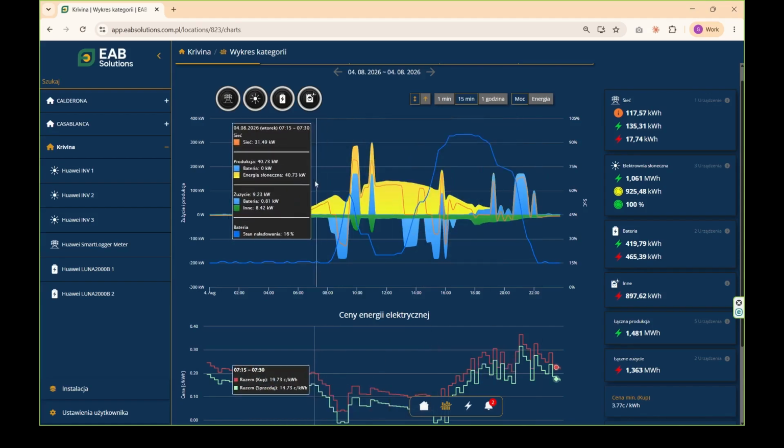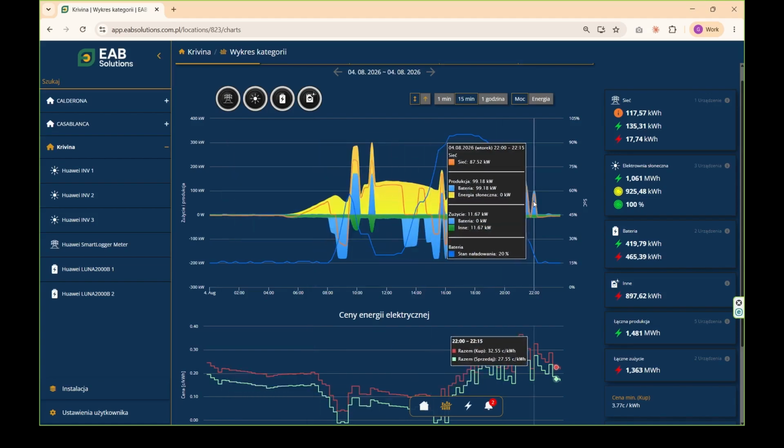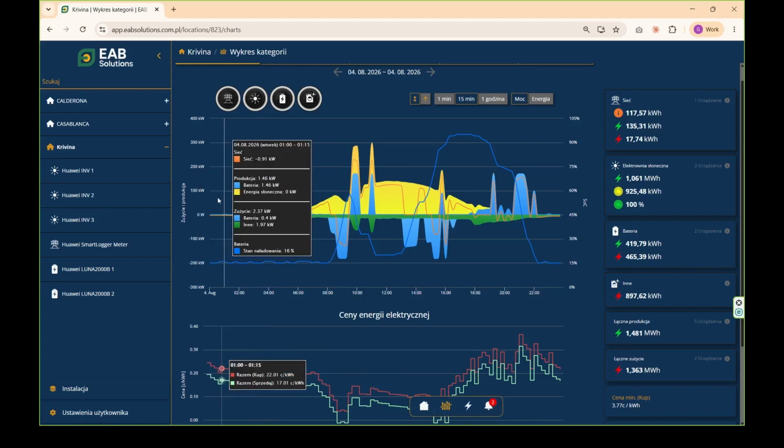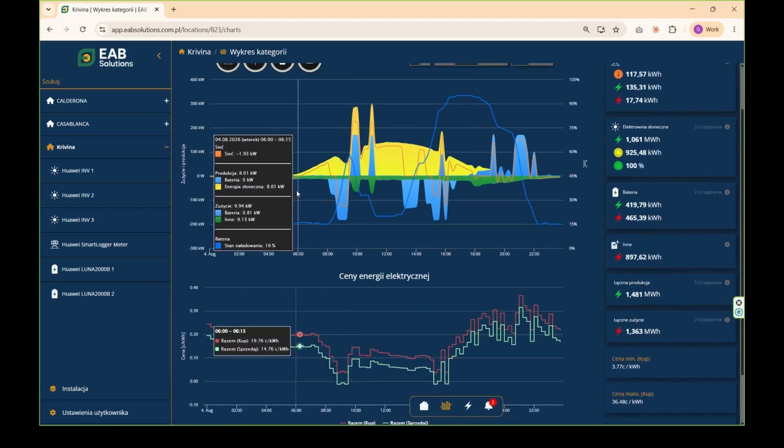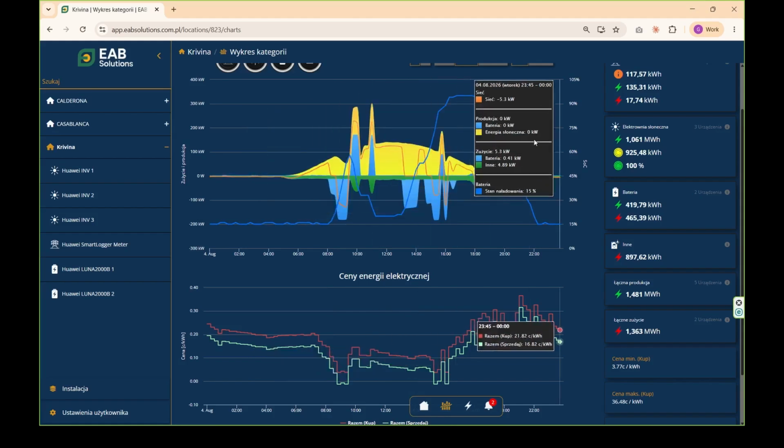There are clients with very intensive consumption inside the peak window between 7 in the morning and 10 at night, and then very low consumption overnight. In those cases, you'd need very large batteries to shift the energy, and it wouldn't be worthwhile. But for the rest of the clients, who have more or less similar consumption between day and night, leaning slightly towards more in the morning and a little less at night, those clients are heavily penalized because they consume more by day than by night, and that is penalized in Poland. With the battery and the PV, we can reduce their daytime consumption, making them consume more at night than during the day. And improving, as I say, those opłata mocowa penalties.